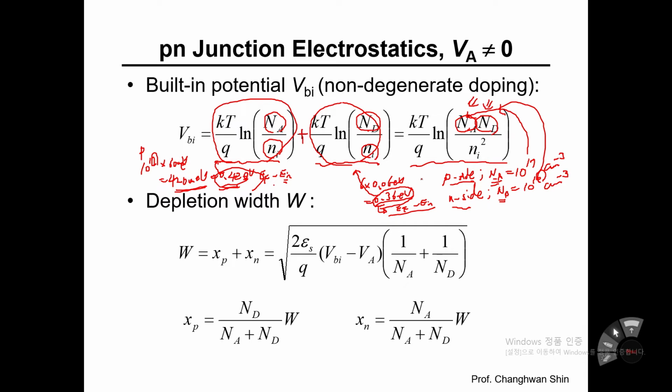Maybe when you were an undergraduate student and had a chance to take a microelectronic circuit analysis class, you may remember that for a given nonlinear circuit including a diode or diodes, the diode can be modeled with a constant voltage drop model, which means a certain amount of voltage is always dropped across the PN junction diode.